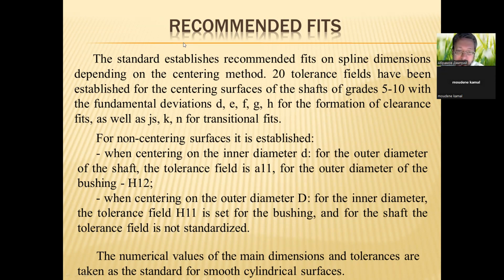For non-centering surfaces, it is established when centering on the inner diameter d: for the outer diameter on the shaft, the tolerance field is a11; for the outer diameter of the bushing, H12, big H.